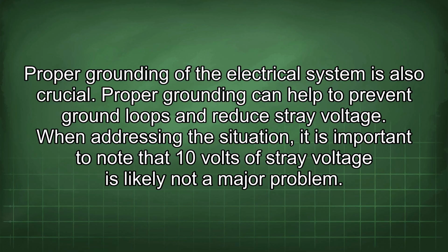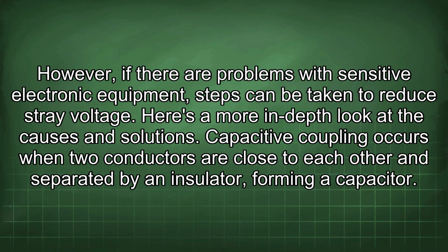When addressing this situation, it is important to note that 10 volts of stray voltage is likely not a major problem. However, if there are problems with sensitive electronic equipment, steps can be taken to reduce stray voltage. Here's a more in-depth look at the causes and solutions.